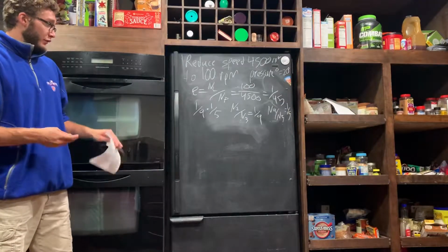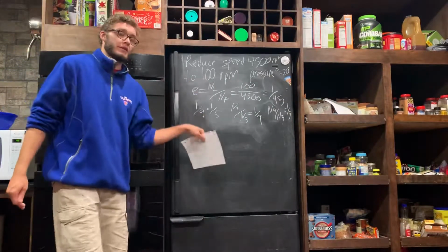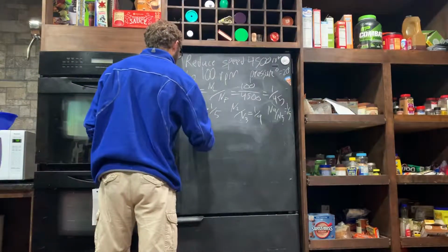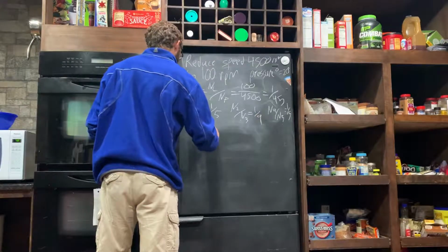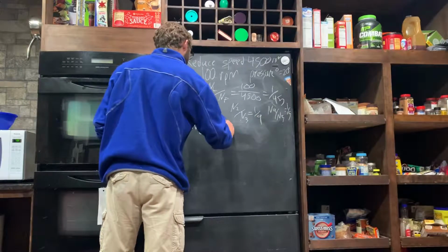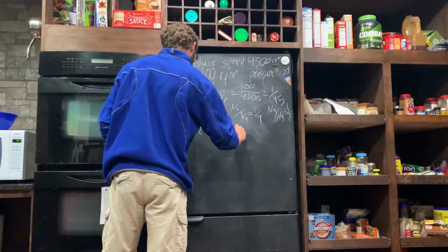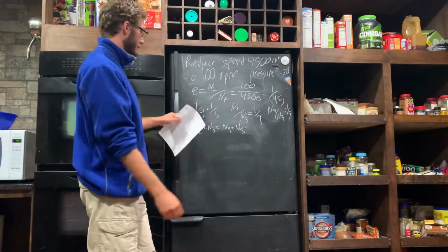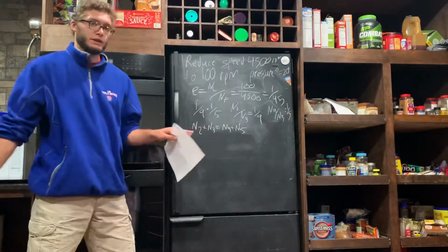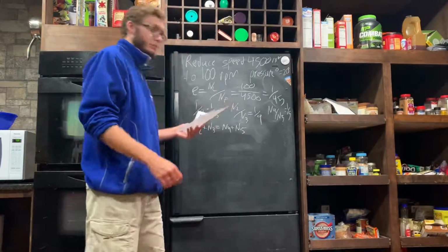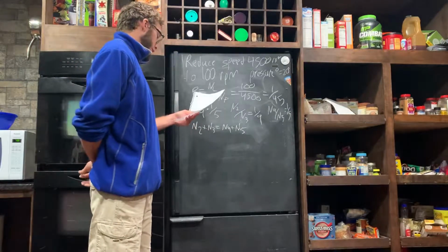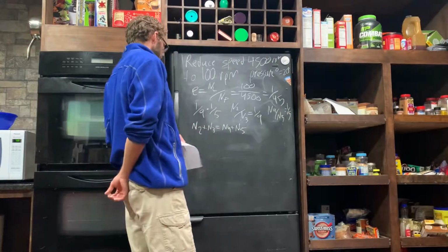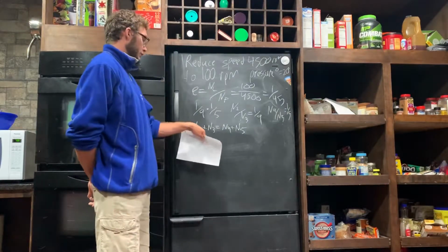Since we want the shaft sizes to be the same, we have N2 plus N3 equals N4 plus N5. Otherwise the shafts would be off, which makes it more complicated to design a square box, or makes the box bigger. Now we go into our equations.